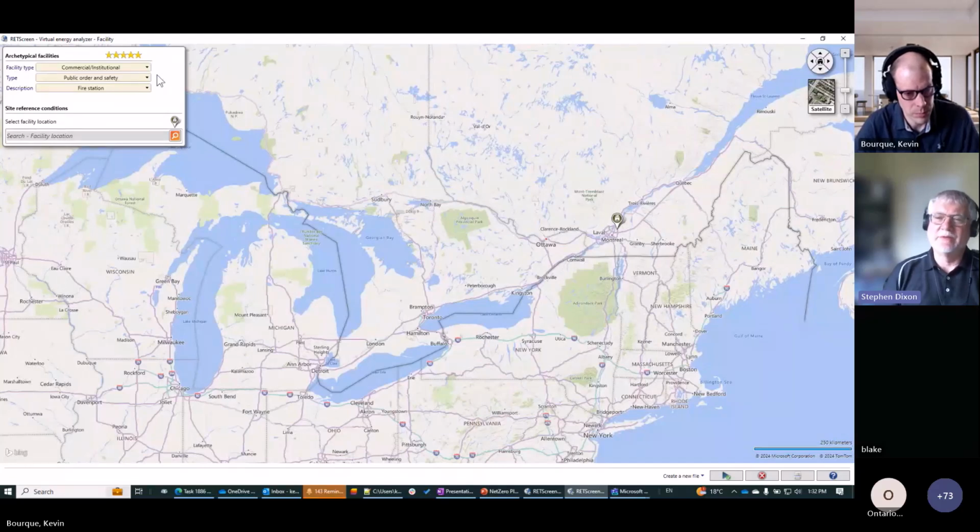No, what we did was ask, how many primary schools do you have? How many middle schools? How many secondary schools? How many offices do you have? We basically took an archetype for each one of those. We set the schedules, we set the temperatures 2 degrees warmer in the summer, and we came up with an answer overall for their portfolio when we multiplied it by the number of buildings. So that's a great way to use the archetype to answer a global question.